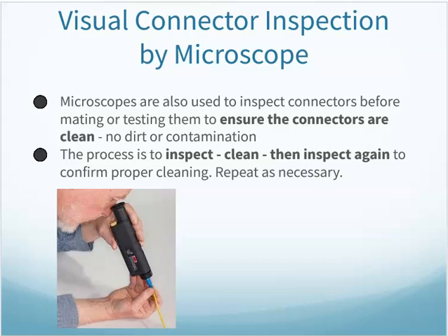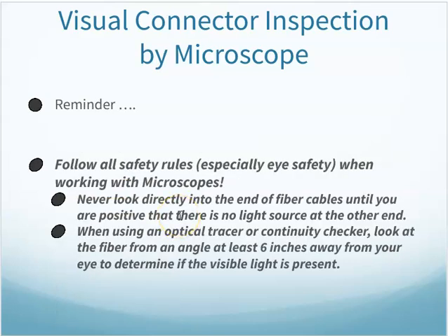Also, I'll remind you, reminder, we need to make sure we don't have that fiber connected to a light source. If you think about the light source going into it normally, going through a fiber microscope, it's now magnifying it 200 or 400 times going into your eye. So we need to make sure that's not connected to a light source before we hook up the microscope.